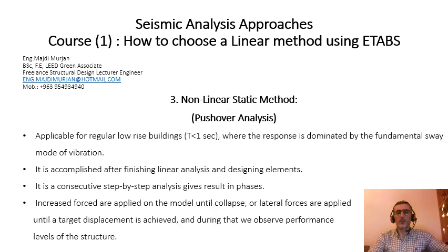Now, what about the nonlinear analysis methods? Let's start with the nonlinear static method, pushover analysis. It is applicable for regular low-rise buildings where T is less than 1 second and the response is dominated by the first mode of vibration.